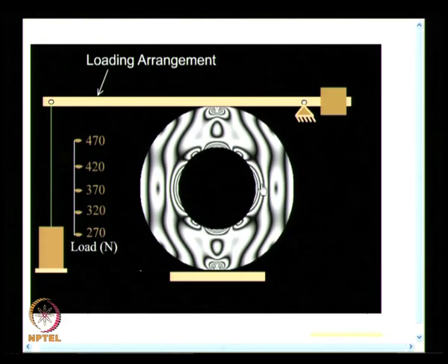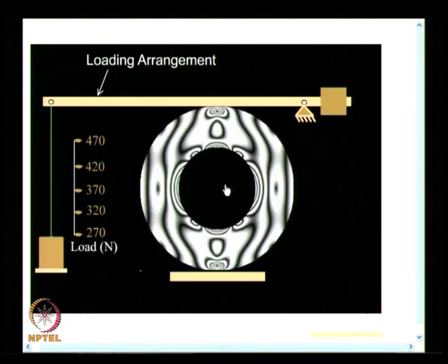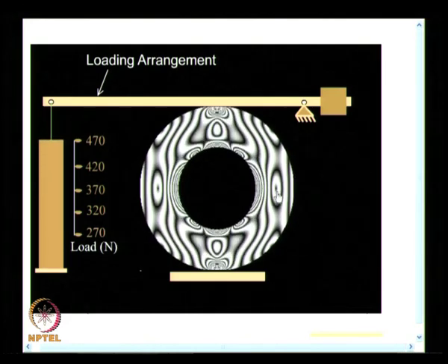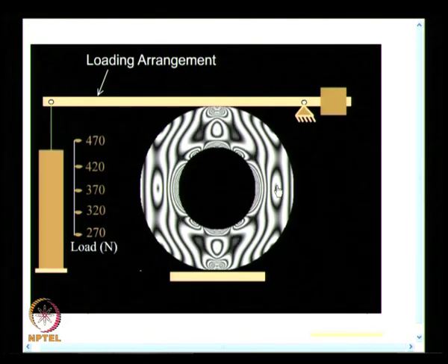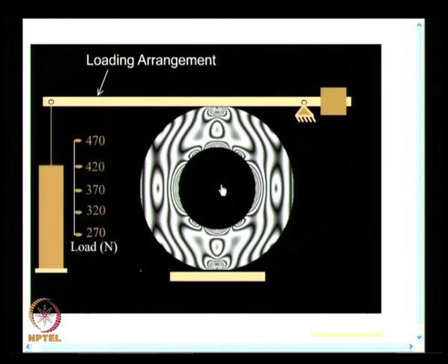And if you are also in a position to look at a plane polariscope, I could verify that all isoclinics pass through this point. So, it depends whether you are given a photograph. If you are given a black and white photograph, it is very difficult to do. You do not have to feel disheartened that you are unable to order a fringe given a photograph. It is not possible. On the other hand, if somebody gives you a color isochromatic, a single photograph, and if you refer to the color code, there is some way to find out the ordering of fringes.